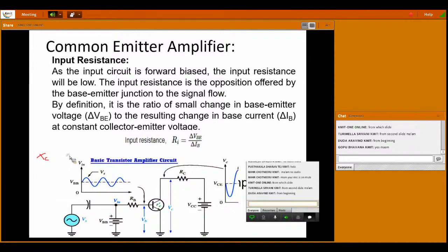If the frequency of the DC signal is 0, the reactance offered by the capacitor becomes infinite. So it is almost acting like an open circuit. Like that, we can block the DC signal and allow only AC signals to the input, the base of your common emitter amplifier.